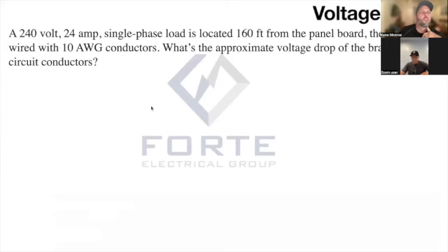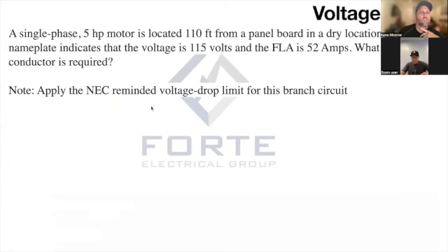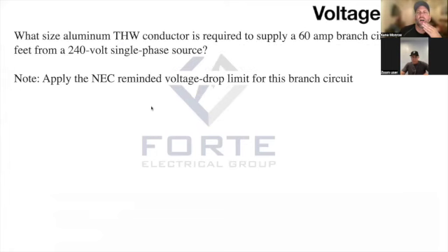Let's get you... Did I put any three-phase in here? Well, let's just do this one. I'm going to flip through these screens so they get recorded, and then you can go back and rework these problems for practice. On this one: what size aluminum THW conductor is required to supply a 60 amp branch circuit 148 feet from a 240 volt single phase source?